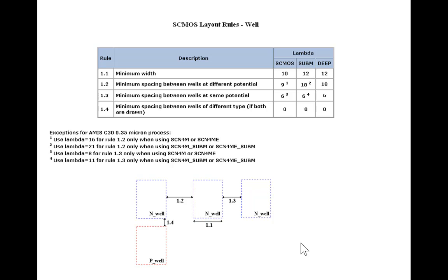Yes, sir. Because the P and N-well will form a P-N junction. Excellent. If it's an N-well and P-well, then at the boundary it forms a P-N junction, and you will bias the N-well to be at a higher voltage than the P, and then this is always a reverse bias P-N junction, and there is a depletion region that is like an insulator to separate them.